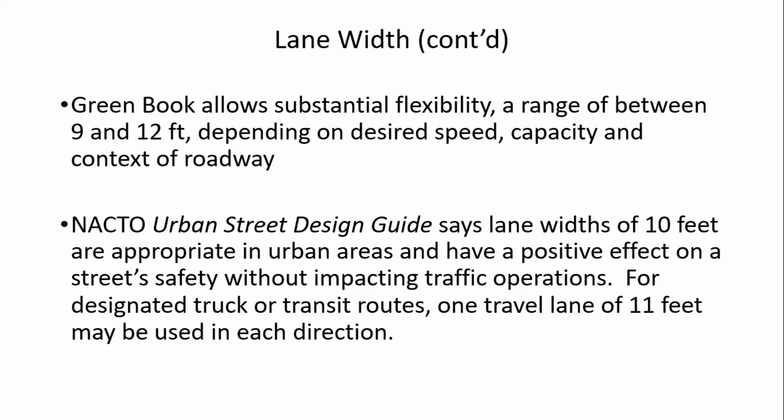I think I talked yesterday a little bit about flexibility, and the Green Book does allow significant flexibility when it comes to lane width. They talk about a range between 9 feet, in a low speed, maybe urban street context where you don't have significant commercial vehicle traffic, all the way up to 12 feet, which would be appropriate, of course, say for a freeway, those types of higher speed controlled access facilities.